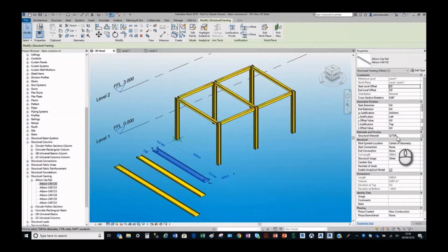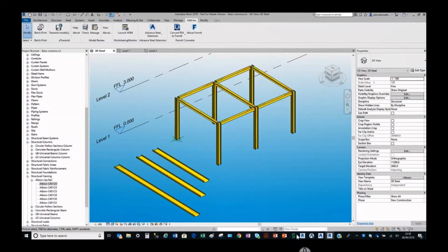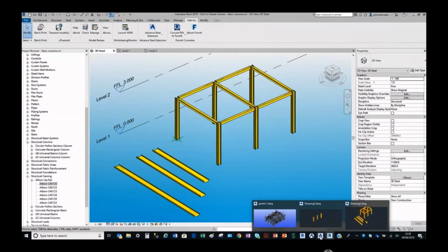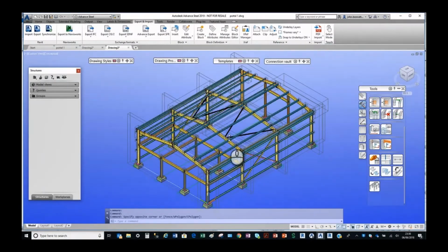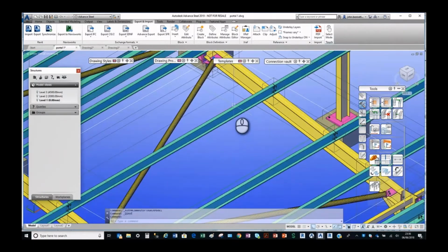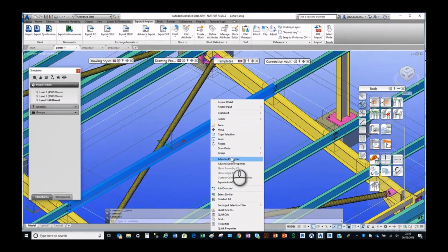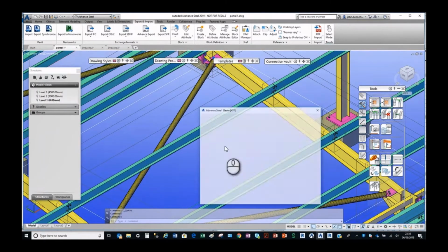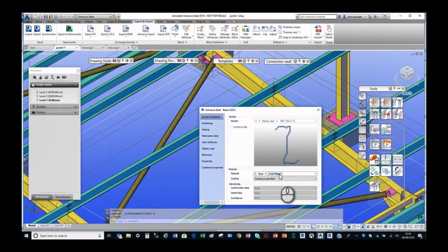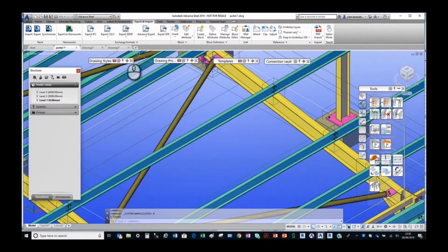What I did was try to create a material inside Revit. When I initially did this, it wouldn't work when I sent it backwards and forwards. I sat there looking at it thinking, I'm sure this works properly because we have cold rolled inside Advanced Steel. So I'm looking here inside Advanced Steel, and under that I can see the material in place here, cold rolled. So I thought, well, it must be. So I created the corresponding material back inside Revit.